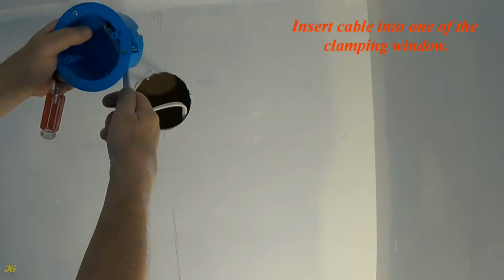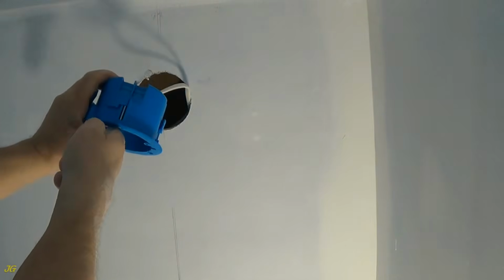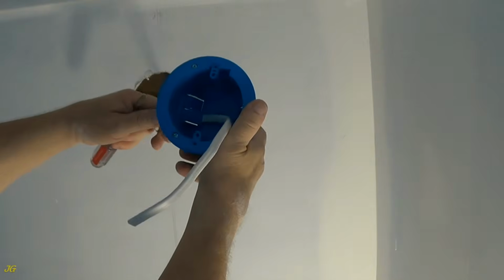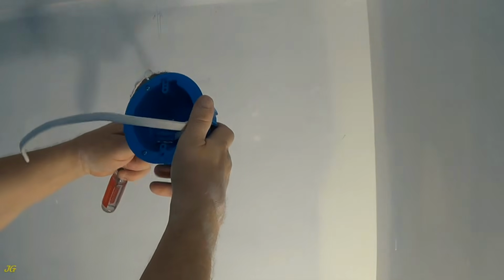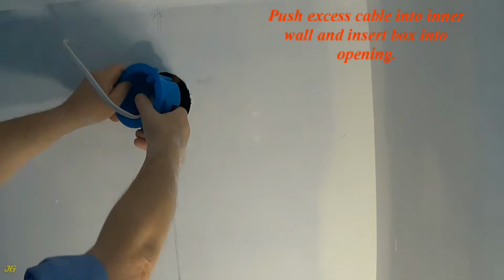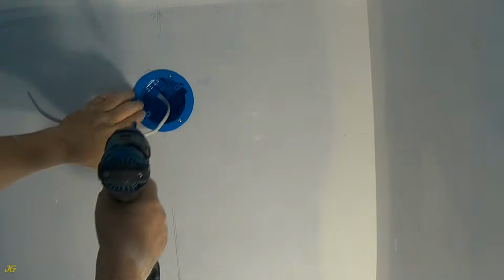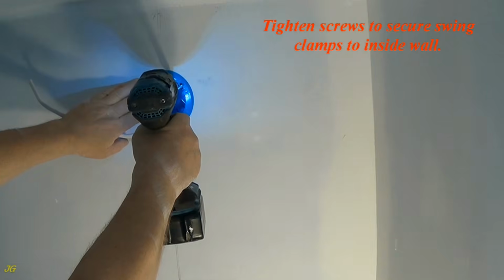Insert cable into one of the clamping windows. Push excess cable into the inner wall and insert the box into the opening. Tighten screws to secure the swing clamps to the inside wall.